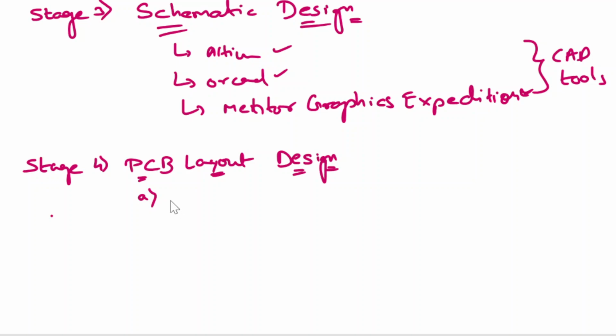So like I was telling, when you talk to the PCB fabricator and ensure that you have the proper vendor, the next thing you have to do is first create a board outline using the CAD tool. For example, if you have a specific requirement from the customer that your PCB should be in such a shape, or of length L and width of certain dimensions, that is the board outline you have to draw in the tool. Then import all the components from the schematic to your CAD tool, and do the component placement.